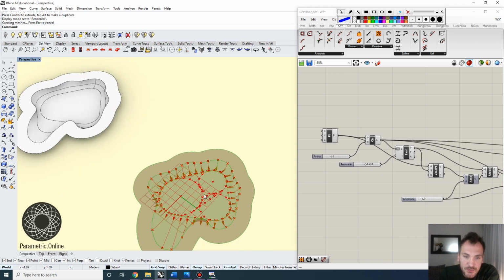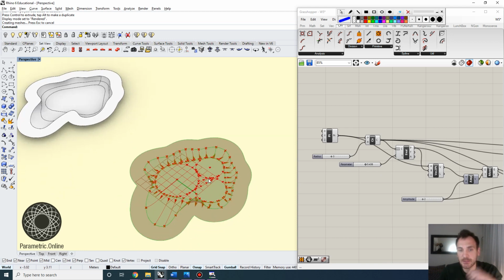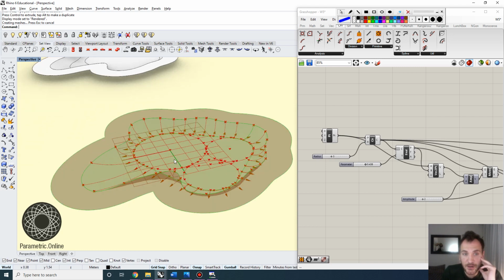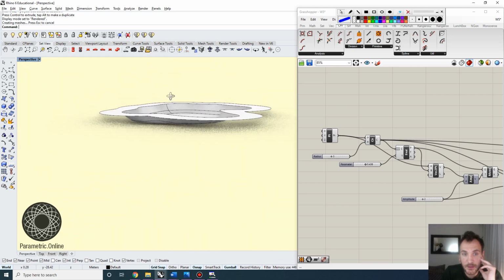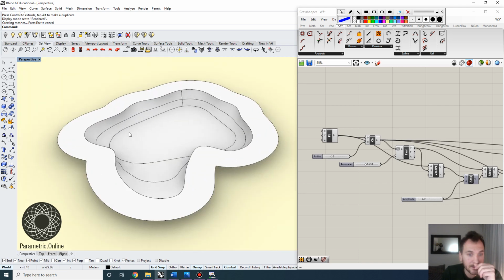For this one, I used multiple circles that can be combined using a single polyline that we're going to compute using convex hulls. Then we're going to do perpendicular frames and find these arch type of profiles, and sweep this profile at the end to get something like this.